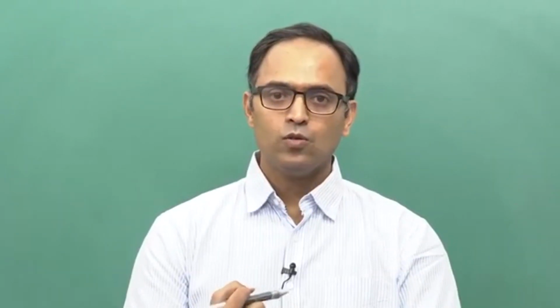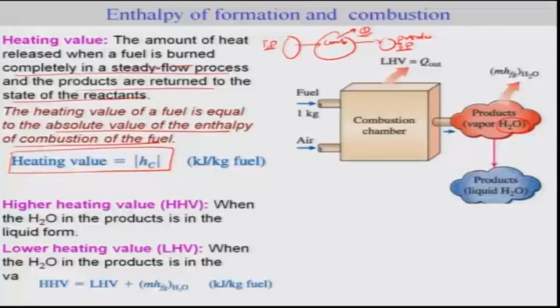So it will reduce the heating value. That heating value, where the product water is in a vapor state, is called the low heating value. If the water is condensed, or if the final product water is in the liquid state, then the latent heat of vaporization is also released as a part of the heating value, and that will be your high heating value.